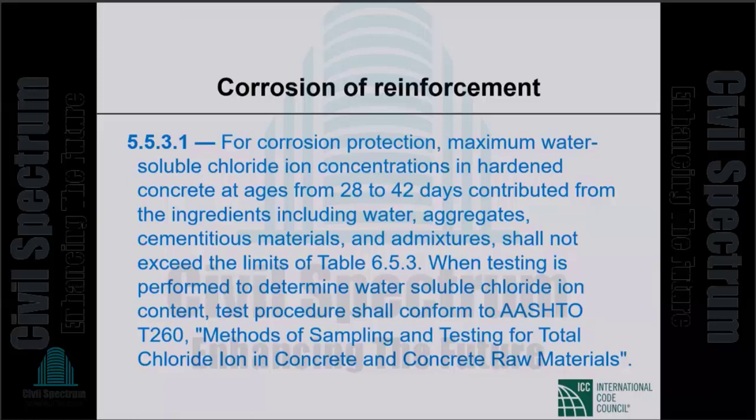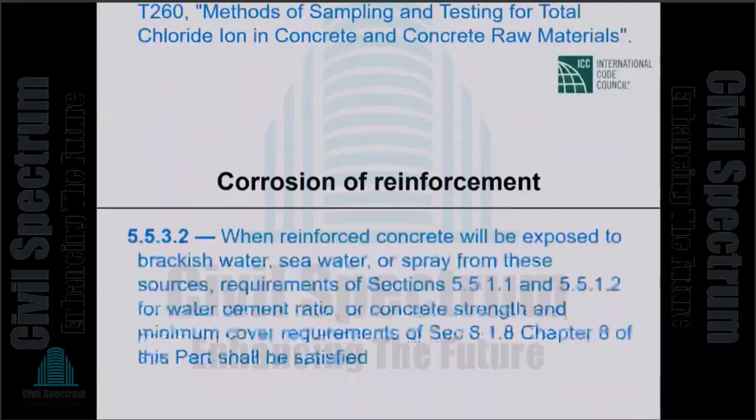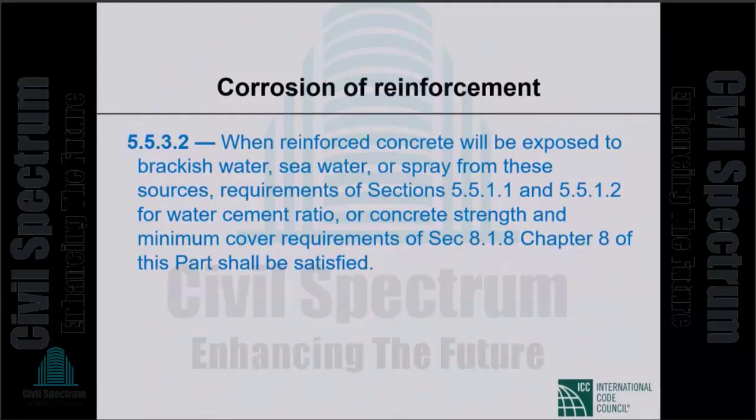There is a table. So if you have a corrosion problem, the chlorides from all sources have to be limited to values given in the table. This is extremely important for Bangladesh. There is a corrosion problem in most of the country, particularly in coastal areas. Chlorides cause the corrosion. The chlorides from all sources have to be limited, severely limited. When testing is performed to determine water-soluble chloride ion content, test procedure shall conform to the AASHTO T260 that I had in mind when I was talking a minute ago.